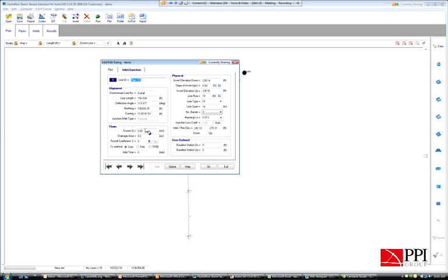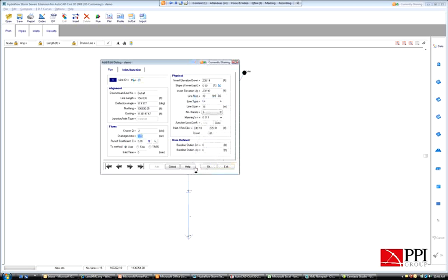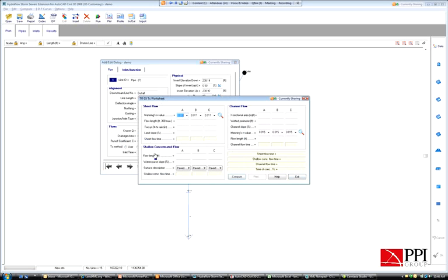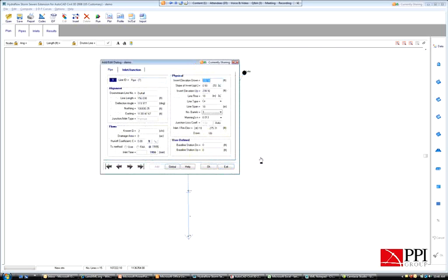But you can come in here and, just for the sake of expediency, I'm just going to enter a known Q into that pipe. Once you've done that and done an edit, I can come in here also and do the drainage area. I can do runoff coefficient or percent, percent up to 3 different areas within that catchment. And I can do a user time of concentration, or it brings you out in a TR55 worksheet, and you can use that to calculate it as well.